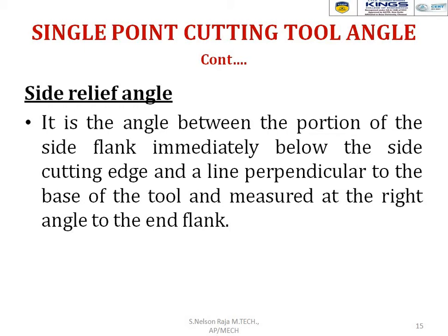It is the angle between the portion of the side flank immediately below the side cutting edge and the line perpendicular to the base of the tool, and measured at right angle to the end flank. This is called the side relief angle. The angle between the portion of the side flank immediately below the end cutting edge and the line perpendicular to the base of the tool. That is the common definition of the side relief angle.